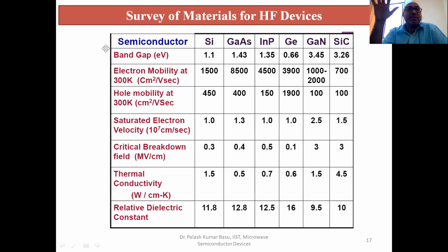Another thing we had a discussion about is that compound semiconductor based CMOS is not a favorable situation. It's not that we cannot make it, but it's not favorable. Gallium arsenide or compound semiconductor is a costly affair, very costly. Silicon in that sense is a little bit cheap, and making CMOS out of silicon is cost effective rather than spending time on gallium arsenide or indium phosphide.